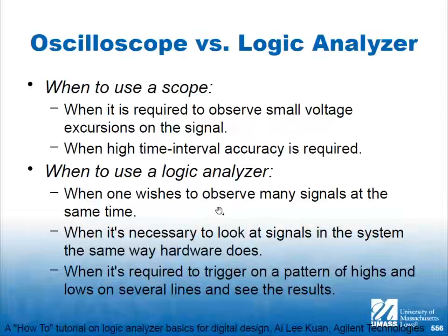So we see many signals, but we don't get the detailed resolution of the signal. We make that concession because we know that it's very likely there is not much resolution to see, especially inside the chip. We shouldn't have analog type of problems on signals inside the chip. I'm specifically talking about FPGAs here. With ASICs, you can, but usually when you have linear problems on an ASIC, it's on the pins.